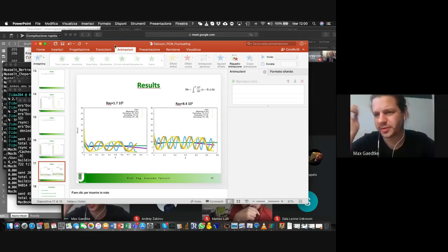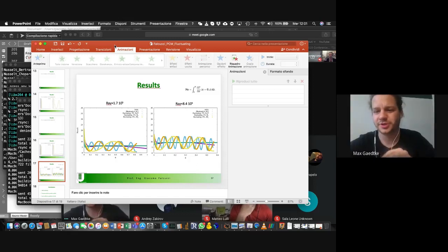The problem with the equilibrium is that you cut off the non-equilibrium part every time step you process, and by that you impose a very strange heat flux in the first cell of your domain. And when you're doing a finite difference calculation for the Nusselt number from the left-hand wall into the domain, you will include that strange heat flux that is unphysically imposed by the boundary condition to your domain, and that could be a reason for your amplification of the Nusselt number.